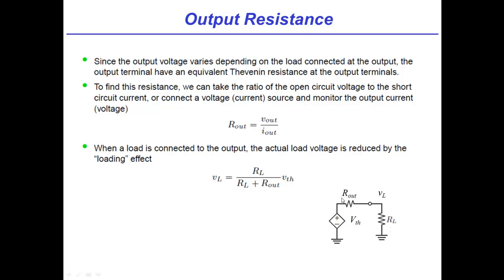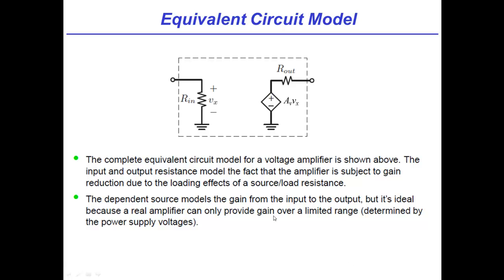That's right. Okay, so we can put these together now, and then we can have an equivalent circuit. The equivalent circuit has all the parts we talked about before. So let's take them one by one. We have the internal input resistance, Rin. We already talked about that. We have the output resistance, Rout. And we have this other element, which now let's talk about specifically, which is a gain element.